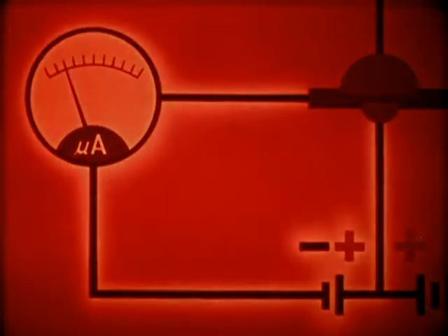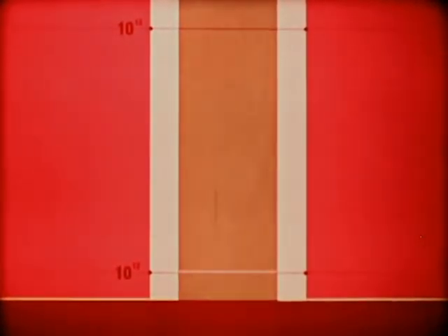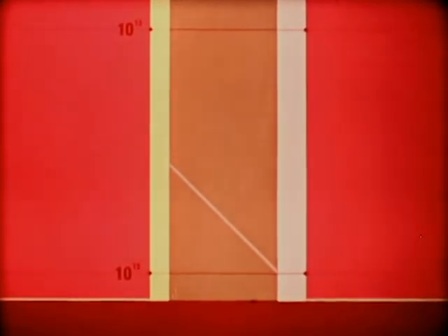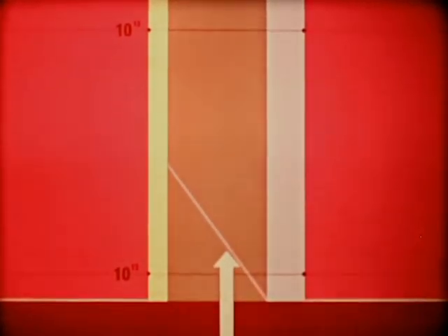We will now consider the concentration curves of the minority carriers plotted in a linear graph. With no voltages applied, the concentration curves are horizontal. But when voltages are applied to both the emitter base junction and the collector base junction, the concentration curve in the base region will be at an angle to the horizontal axis.